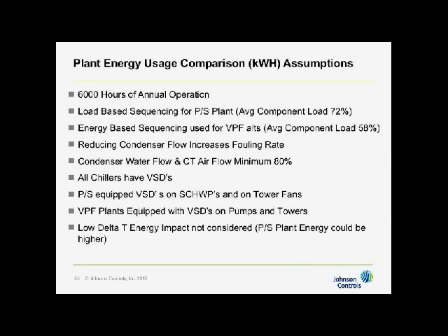Condenser water flow rate and cooling tower fan flow, we reduced to 80%. Now, we looked at several different reductions. We looked at 90%. We looked at 80%. We took it down to around 70% where we saw a crossover. There are many considerations. We'll get into that later on, but we ended up at 80% of condenser water and cooling tower airflow.